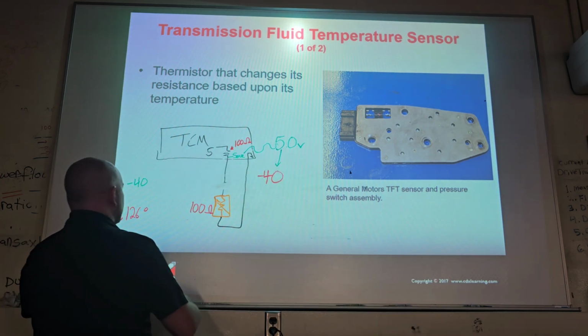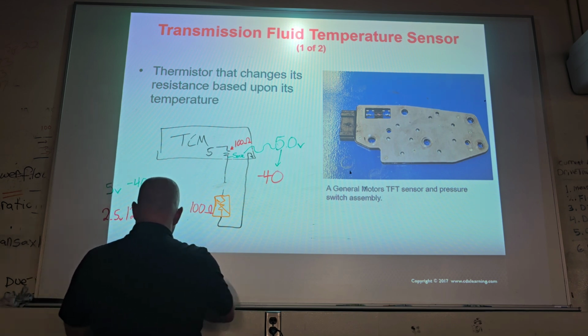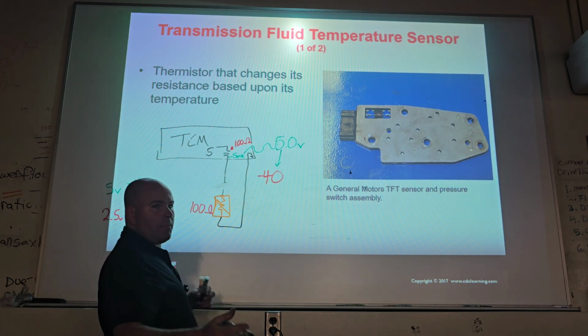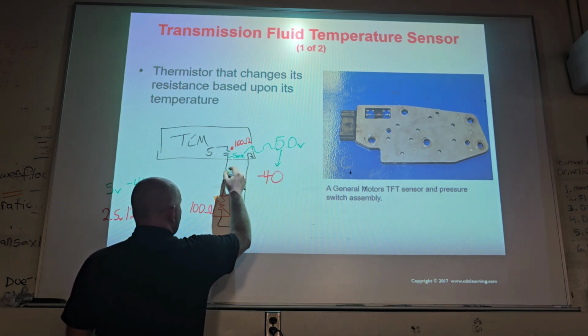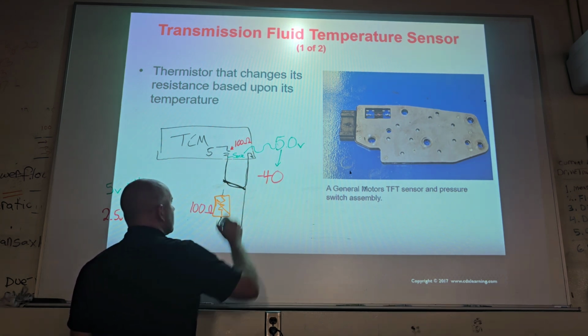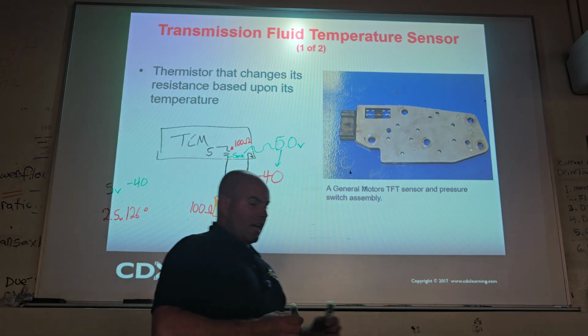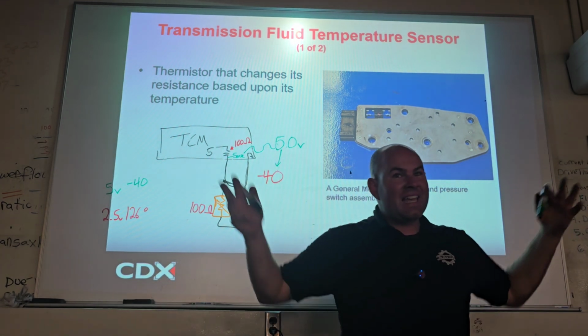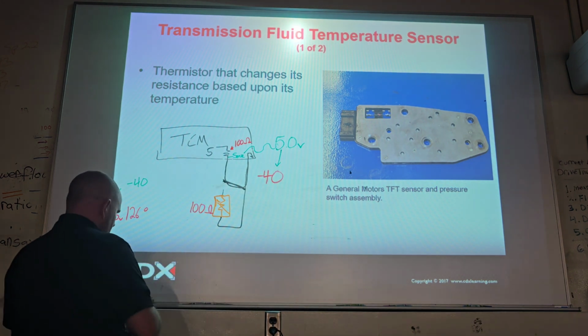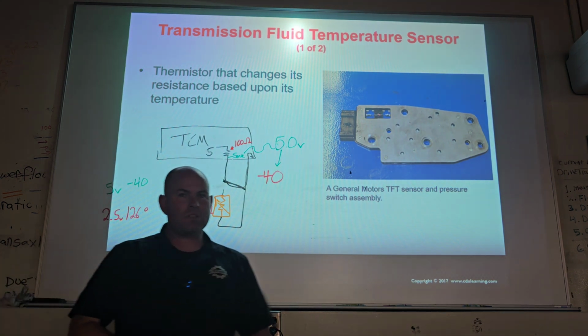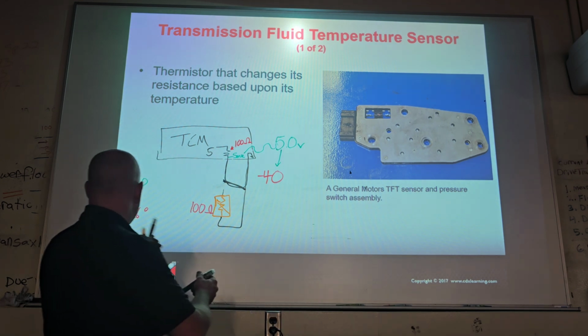We'll do one more just so you're very thorough. Let's just say on transmission assembly, we put the valve body back on and we clamp these 2 wires together right here. And now it just does this. Any ideas what that one's going to read? That is a short. So what's it going to read? What do you think? 3, yeah, on there, exactly.